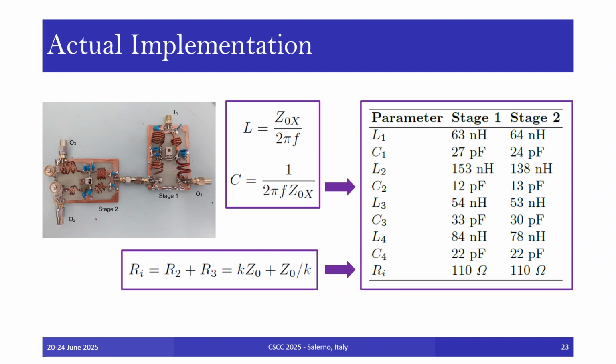The thin film deposition process also allows for very stable, precise resistance values with excellent temperature coefficients. This precision helps maintain consistent performance over a wide range of frequencies and high power operating conditions.